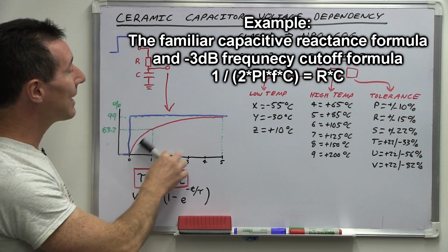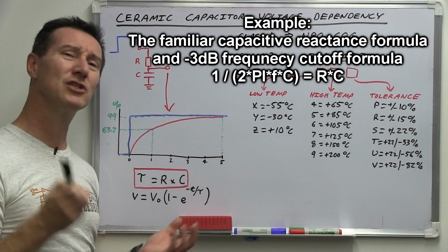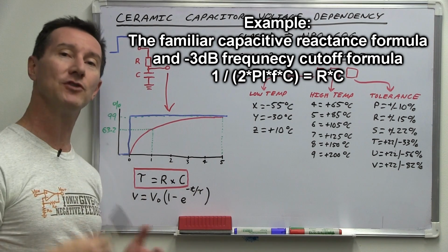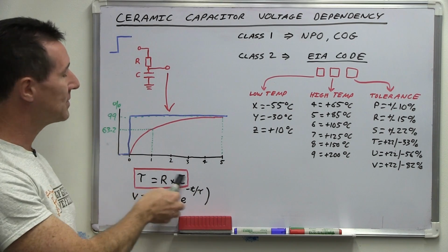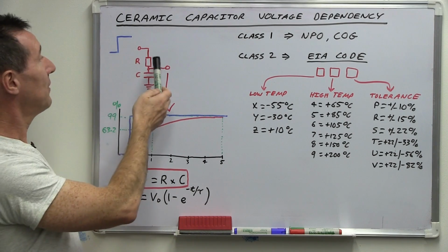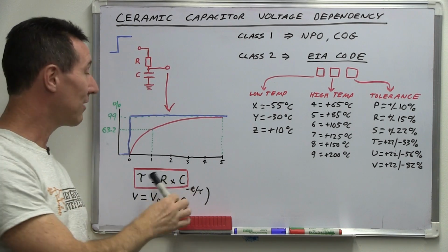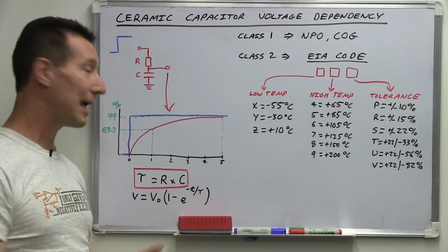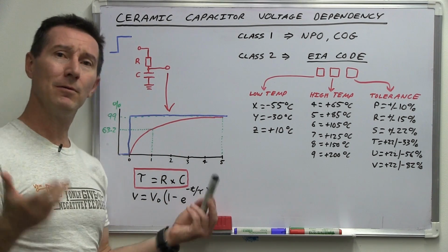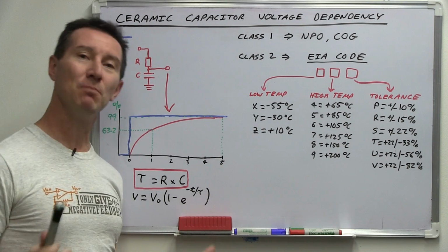And basically a capacitor is essentially fully charged, you could say, after roughly 5 time constants, or 5 times RC. A capacitor is fully charged. So if you know your resistance, you know your capacitance, you can figure out how long it takes to fully charge that cap or get to 1 time constant. Pretty simple, pretty basic. And of course there's more to this as well.